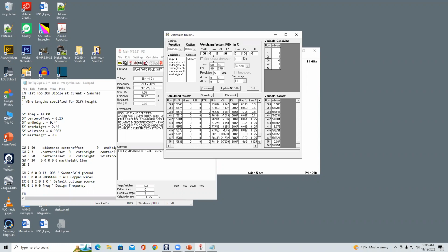But you can't make a general statement that the lowest SWR from a given impedance for some other characteristic impedance is necessarily at x equals 0. I think it's trying to get rid of the imaginary aspect.